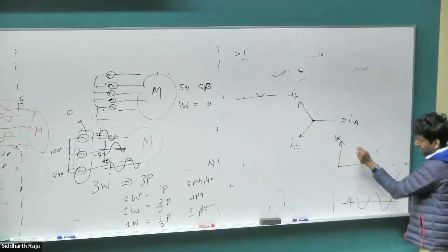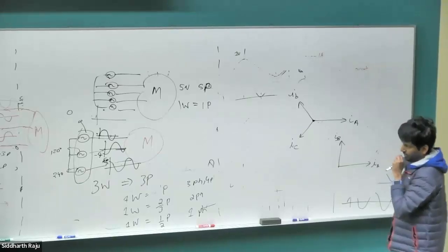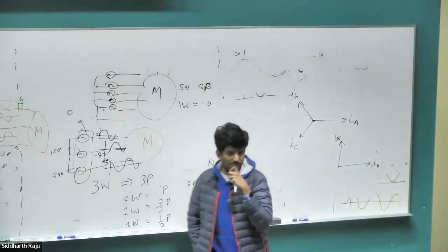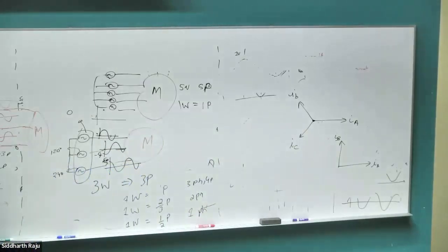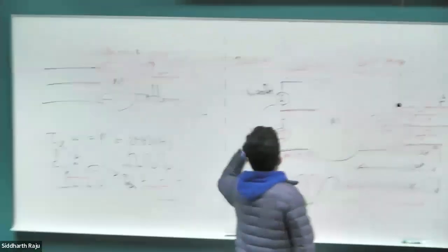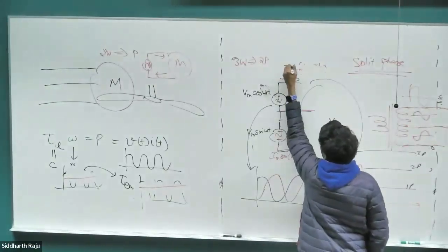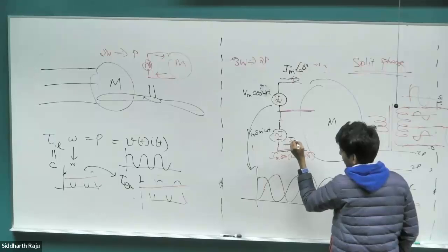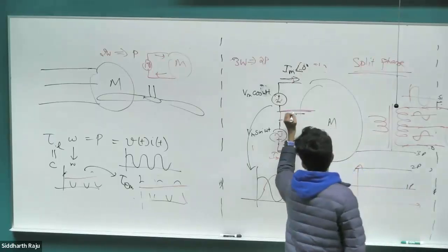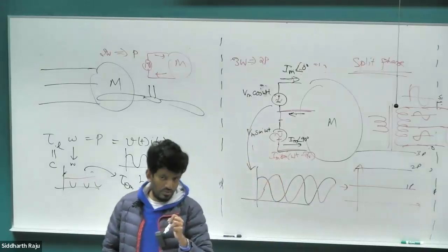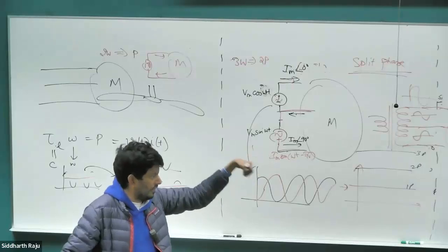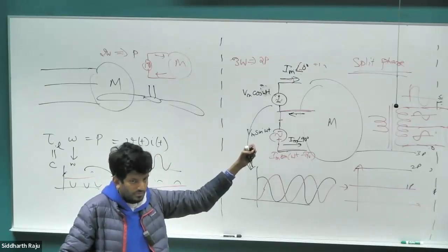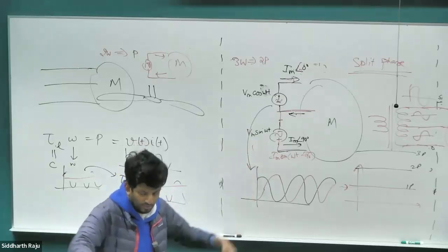So we have our current IA here, IB here. Let's say this magnitude is same as this magnitude. How do I find the current at the return conductor? In the phasor representation that I have, this current is some magnitude Im at some angle 0-degree, let's say, and this current is Im at some angle 90-degree in our phasor domain. What is going to be the total return current? How will we figure it out using phasors? The reason we went to phasors is so that we can do this diagrammatically without having to break our head. So how will you do that? What will be the sum? Just a vector addition, right through the middle.